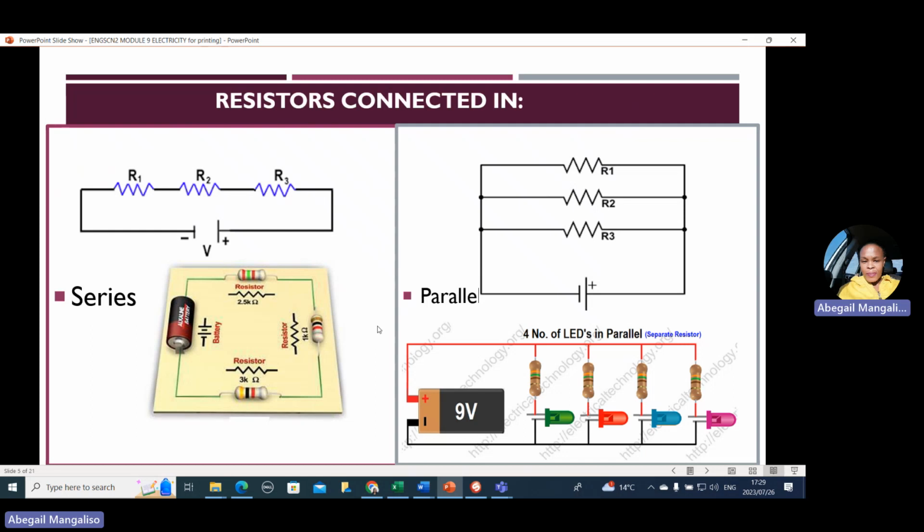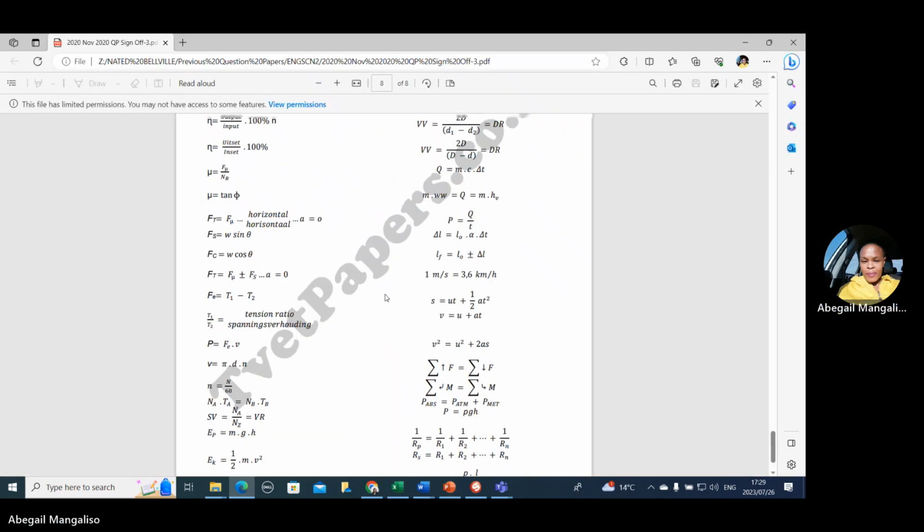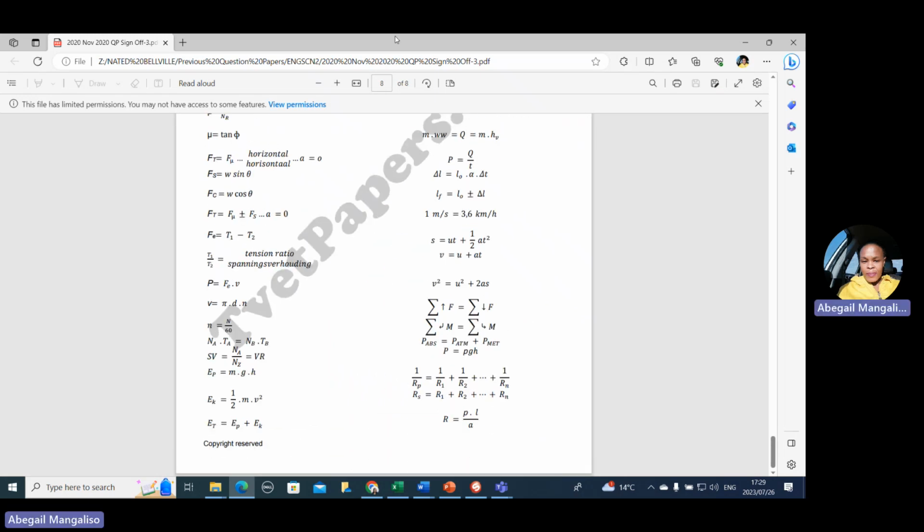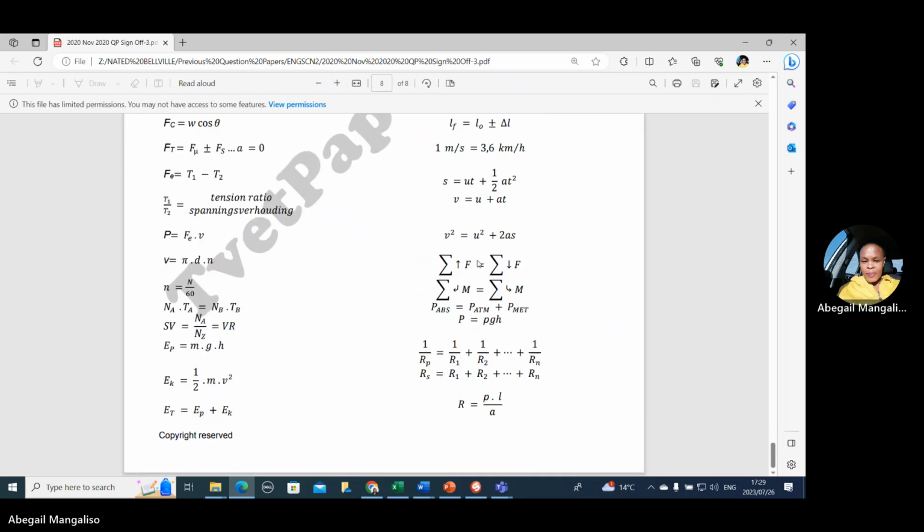Okay, let's look at the activity. An example. First, look at the formulas. The formula for series will be given. The formula for parallel is given as 1 over R, plus 1 over R. All you need to remember is to do the inverse. So you can keep this side as RP because you don't calculate 1 over RP, you calculate RP. But this side you put brackets, all to the power negative 1.